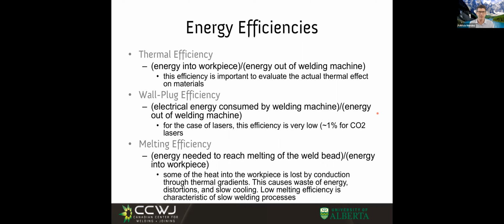And melting efficiency is this. In welding, in fusion welding, we need to melt to have a joint. Now, if all I wanted is to melt, I could bring the weld pool to the melting temperature and not one bit more, and the rest of the plate could be at just the original temperature, and that would be perfect.